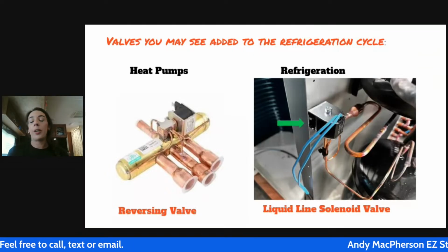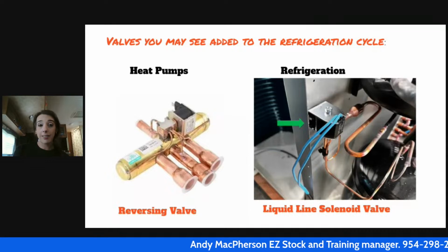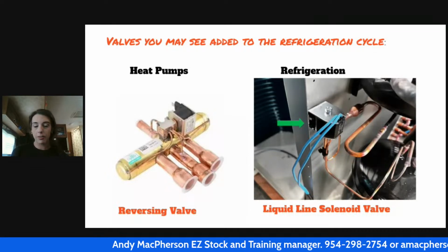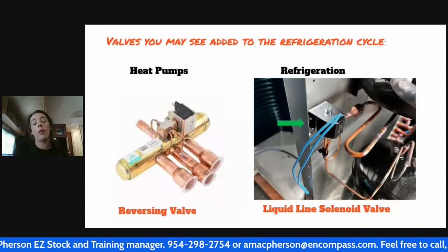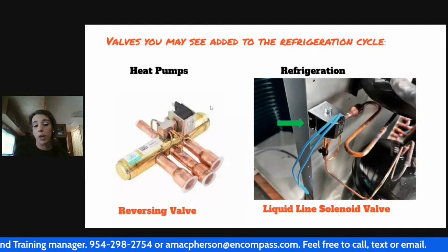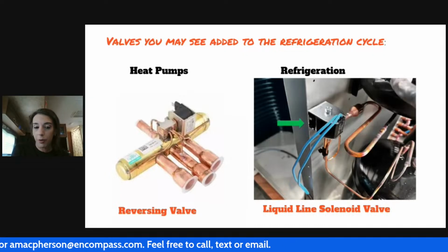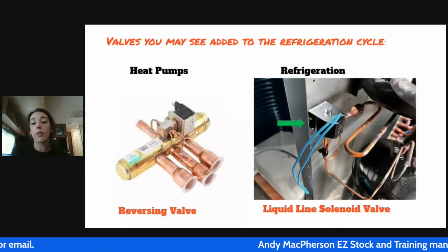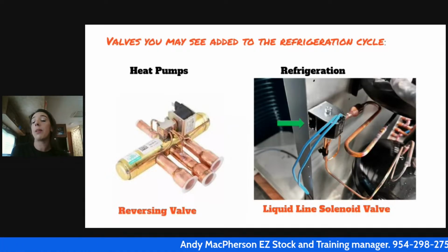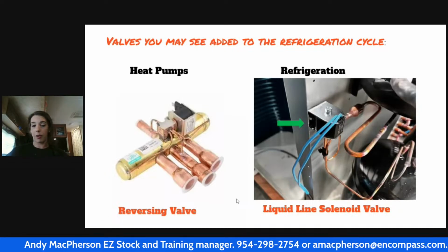Now, I like to add this in. It's not super important for what we're doing right now, but there probably are a lot of restaurant techs that watch these, especially for Encompass. So I just want to go over it very, very quickly. In the residential world and in the commercial world, we'll see a lot of heat pumps. If it's a heat pump, it has a reversing valve, okay? That reversing valve is solely responsible for deciding which direction the refrigerant flows. So it's going to be the first component that our refrigerant comes to after that disconnect is turned on and that thermostat is calling.